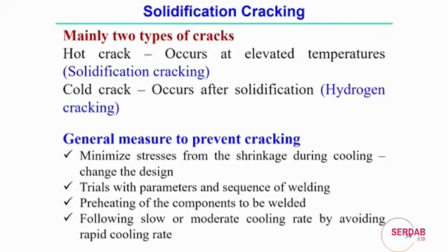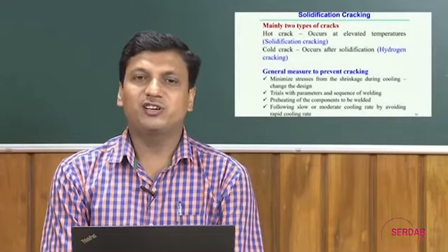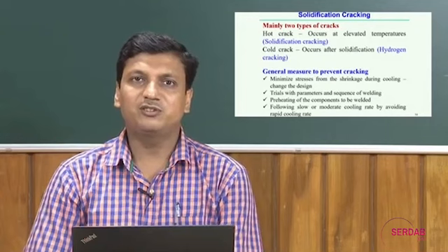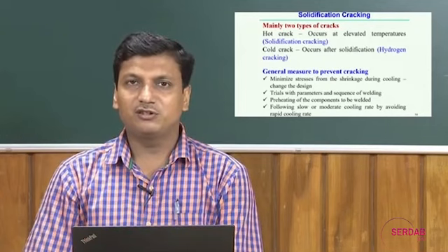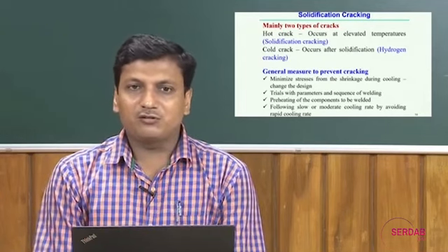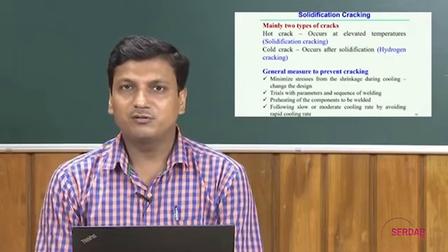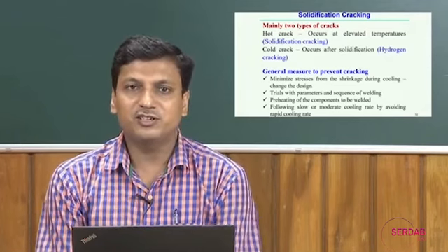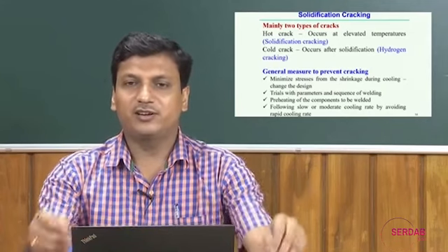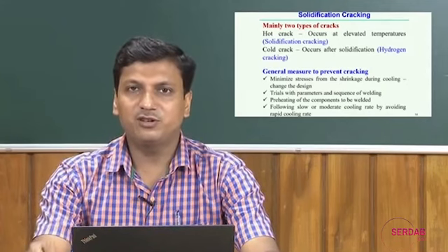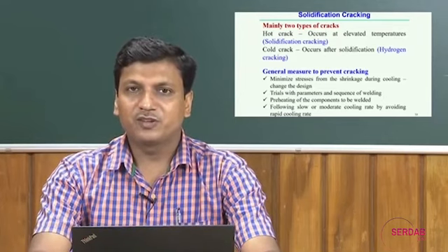But of course, these two cracking phenomena depend on several parameters, but mostly they are linked with the metallurgical transformation that occurs throughout the solidification period. But what are the general measures or precautions necessary to prevent the cracking phenomena in the welding process? If we look into those points, first always try to minimize the stresses from the shrinkage during